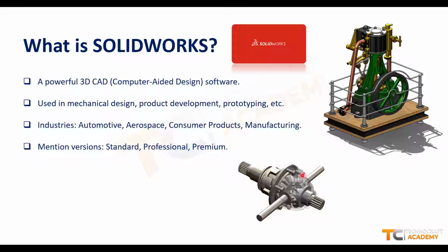All the nuts and bolts you could see here. You don't need to design them. In the SolidWorks design library, you can get all the fasteners ready. You just need to drag and drop it, and it will give all the shape, size, and formats, everything. This is the biggest advantage here. With that, you're going to have SolidWorks Visualize Standard, which is again free, and CAM is also with this, and some of the basic simulation will be here.